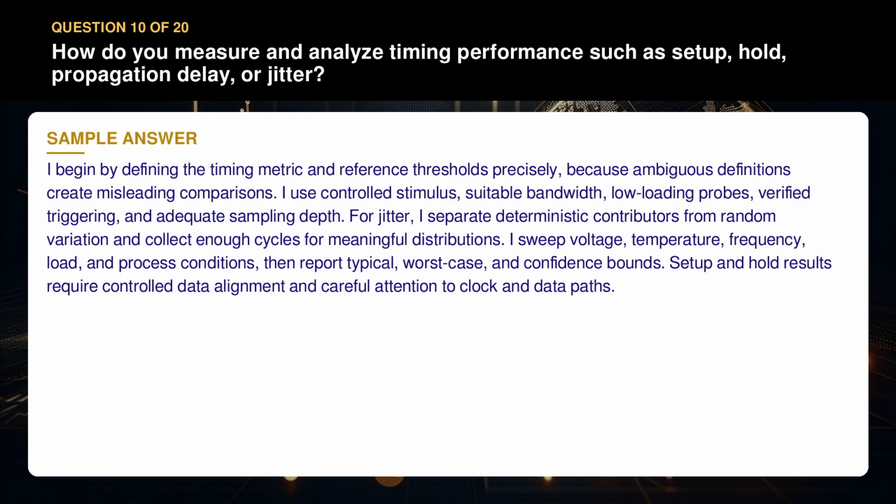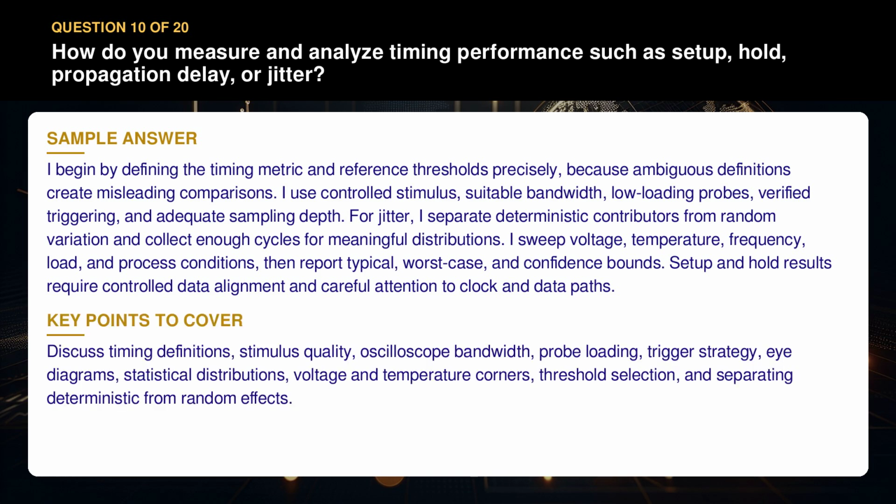Setup and hold results require controlled data alignment and careful attention to clock and data paths. Discuss timing definitions, stimulus quality, oscilloscope bandwidth, probe loading, trigger strategy, eye diagrams, statistical distributions, voltage and temperature corners, threshold selection, and separating deterministic from random effects.